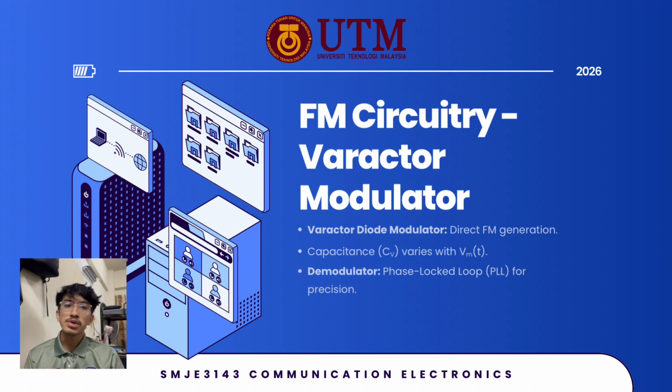Regarding FM circuitry, I examined the varactor diode modulator. The varactor acts as a voltage control capacitor. As the message voltage changes, the diode's capacitance varies, which directly shifts the resonant frequency of the LC tank circuit. This is a highly effective method for direct FM generation.